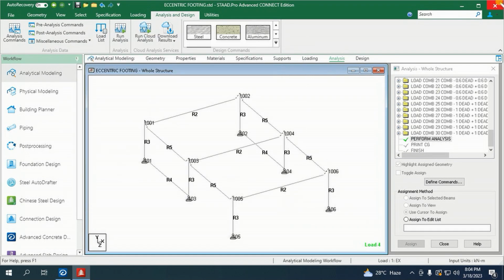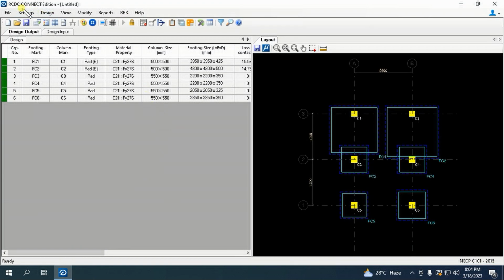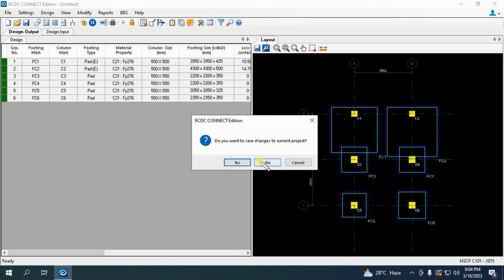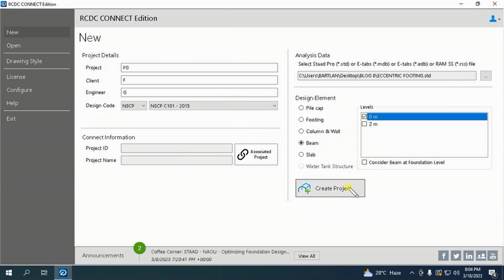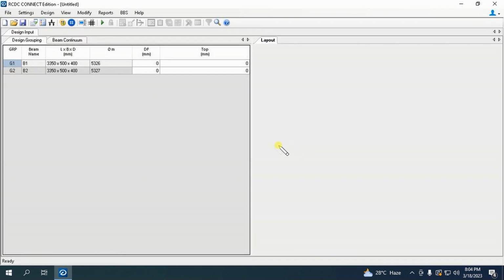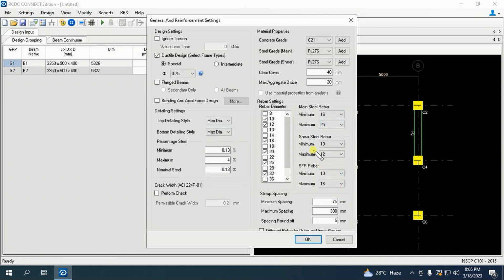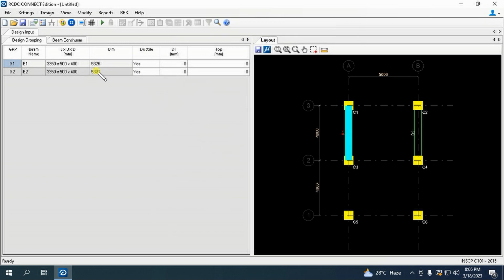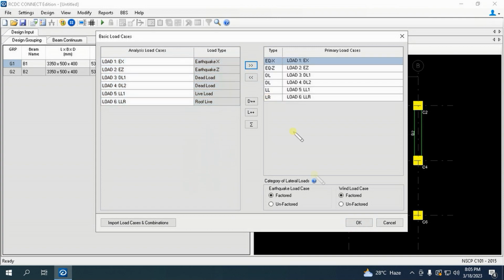Now we will exit this Staad and check the footing dimensions again, to see if changes take place after the change in column dimension and moment application. We will confirm that the strap beams and grid beams are not affected by the moment applied to the columns, though it is definite that the strap beams are not affected by the column increase we made.